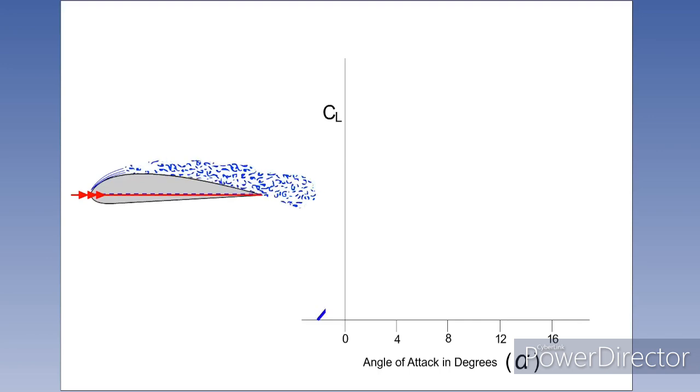The coefficient of lift, or CL, of an aerofoil increases with angle of attack up to a maximum, CL max. Any further increase above this critical angle of attack or stalling angle will make it impossible for the airflow to follow the upper contour of the wing smoothly. The flow will separate from the surface, causing CL to decrease and drag to increase rapidly.